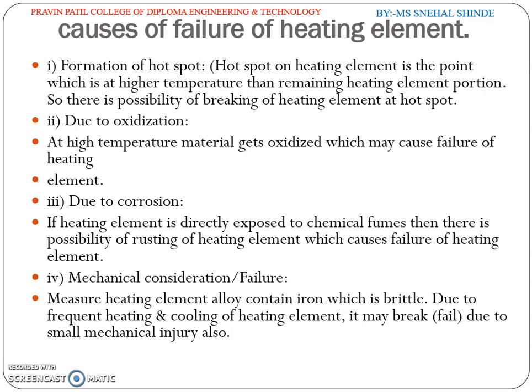So the frequent heating and cooling of the heating element may also break it due to mechanical injury or force upon the heating element. Then corrosion happens because it is exposed to chemical fumes or naturally available gases, so it gets corroded and there are chances of failure of the heating element.